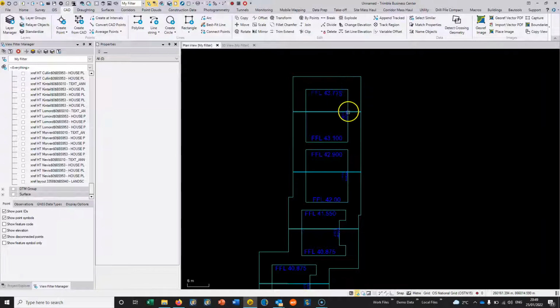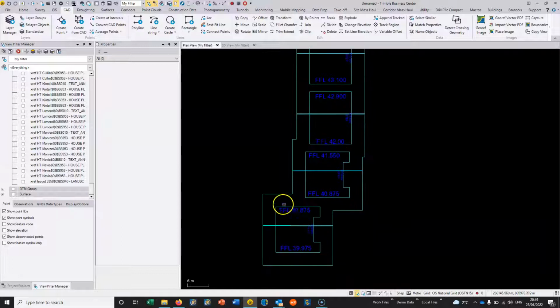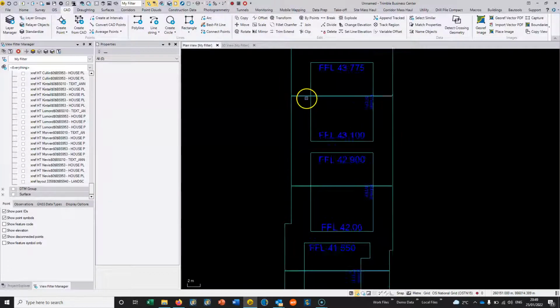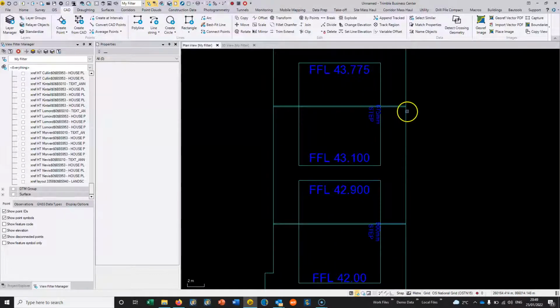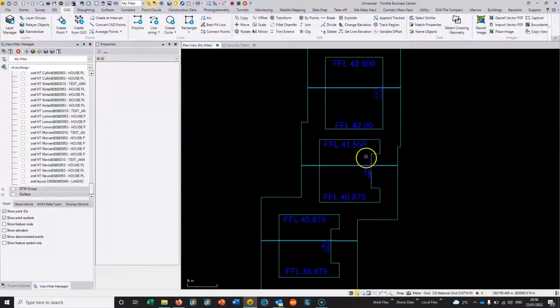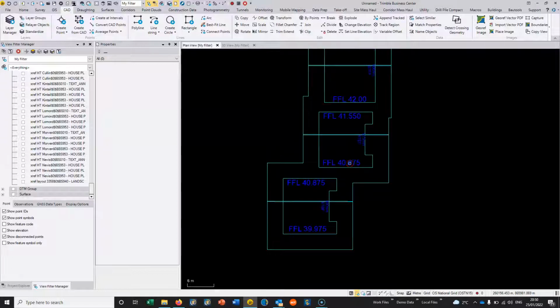3 meters all the way around, and then I've basically joined them because you're obviously going to create that as a single platform. And then what we've done is we have drawn a line perpendicular to the midpoints of these 2, because this is split platforms. And then we've moved the step in the platforms 1 meter off center, because the lower platform would generally extend into the upper platform by around that amount.